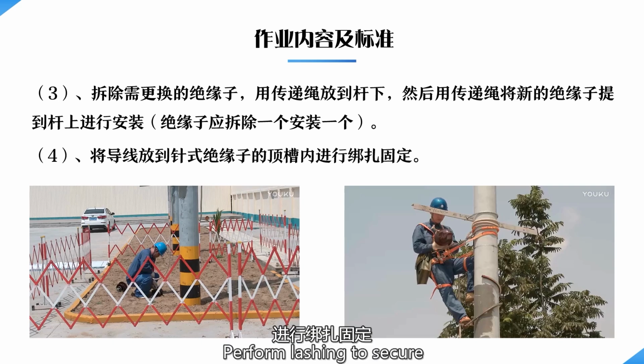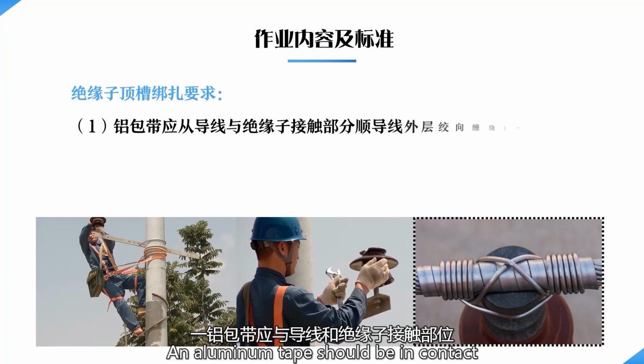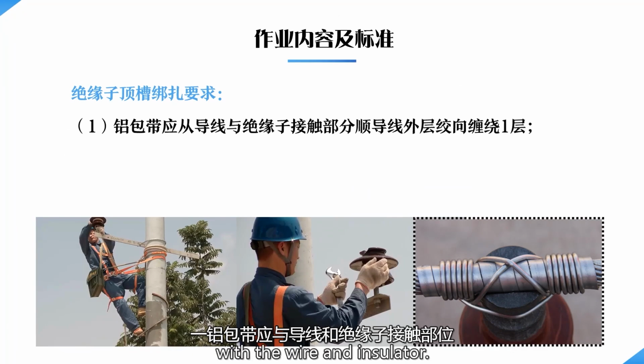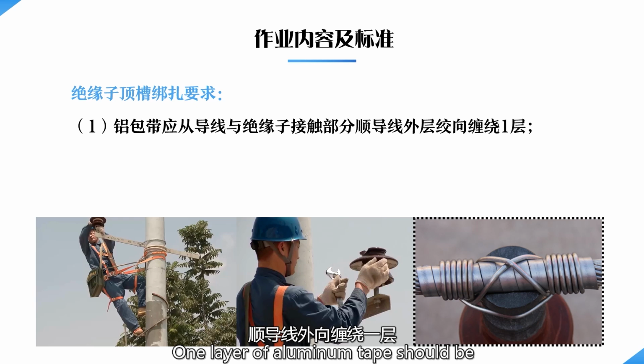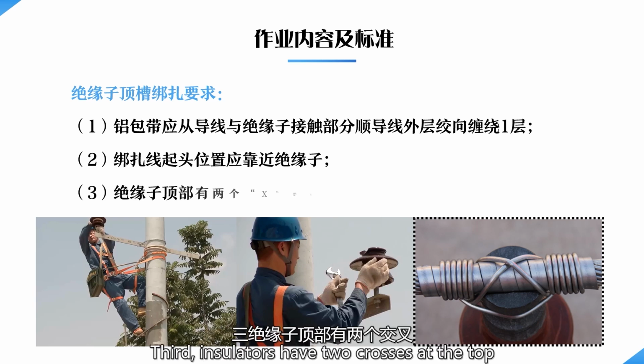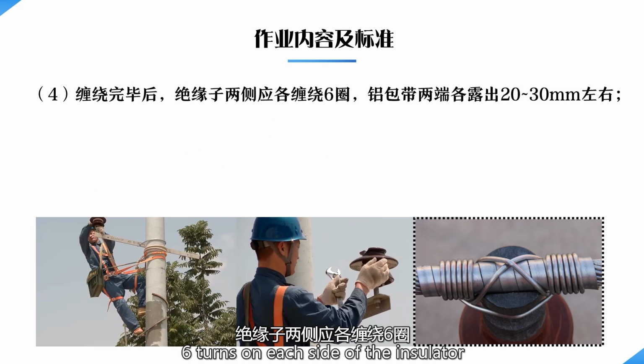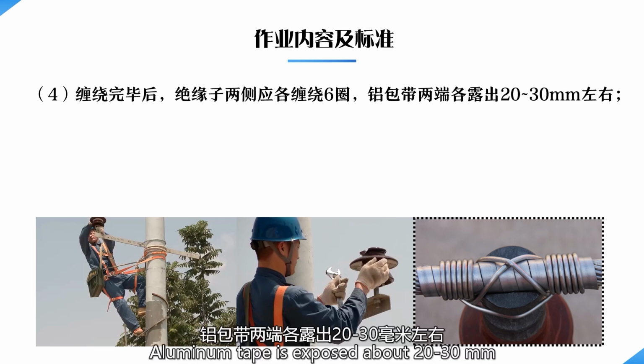4. Place the wire in the top groove of the pin insulator. Perform lashing to secure. Top lashing requirements for insulators. An aluminum tape should be in contact with the wire and insulator. 1st, a layer of aluminum tape should be wrapped around the wire in an outward direction. 2nd, the starting position of the tying line should be close to the insulator. 3rd, insulators have 2 crosses at the top. 4th, after winding, 6 turns on each side of the insulator. Aluminum tape is exposed about 20 to 30 millimeters at each end.